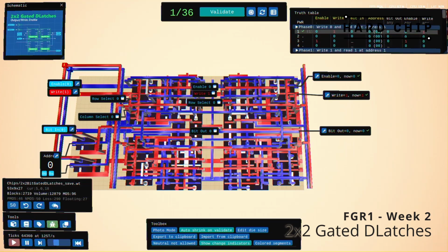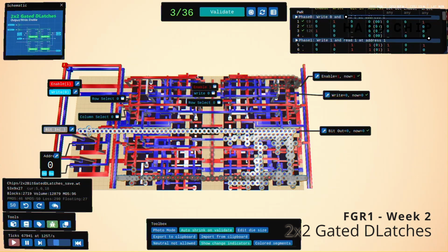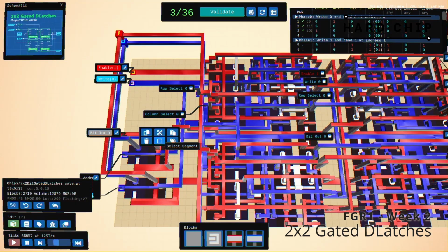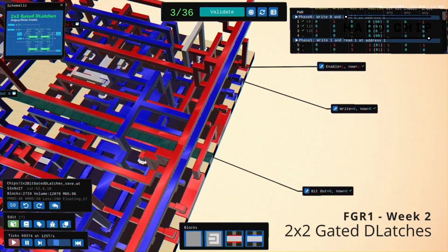So here we are writing 0 byte into address 0. So it should be written right now. If I do this, it clears any flag, so no enable, no write. It maintains the data on the byte in, so the cell is sure to have that value until the flags are cleared. And then if we enable our bit in, which is just the data bus, and if I select properly, yes, it will be our byte out.